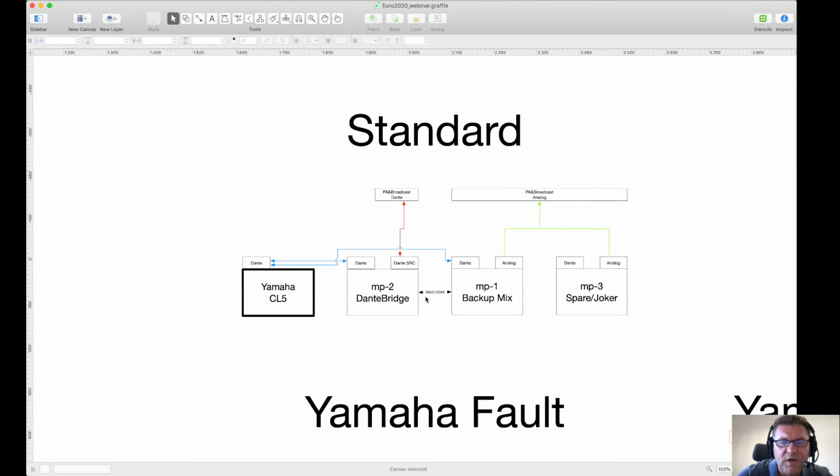If everything worked in the right direction, which was the case, fortunately, the standard situation would have been the MP2 bridge getting the feeds from the microphones locally, getting the feeds from the stage for the radio microphones, making the exchange back and forth between the Dante external, let's call it like that, and the Dante internal, having Pro Tools connected to both the Prodigy MPs, for a fully redundant, much more than redundant, Pro Tools managed by the Prodigy and then injected into Dante for the console.